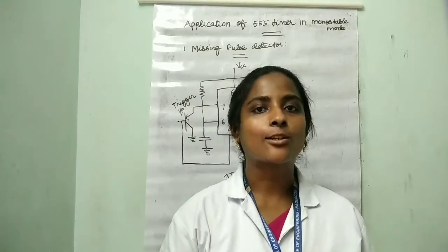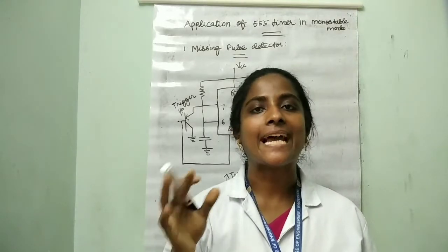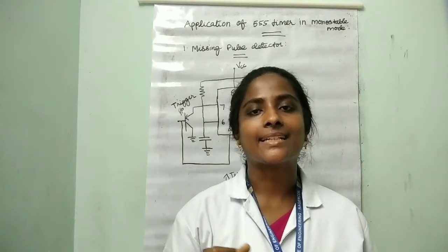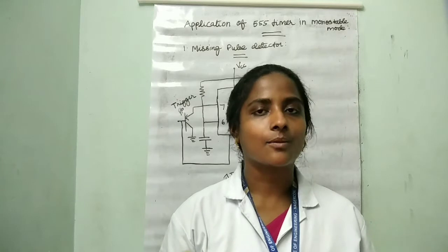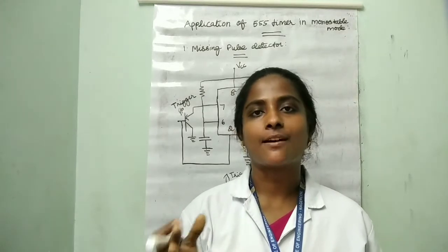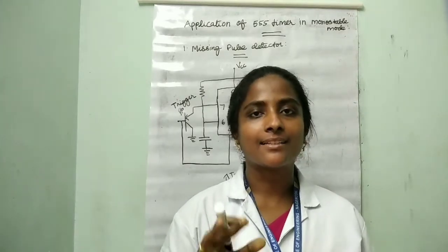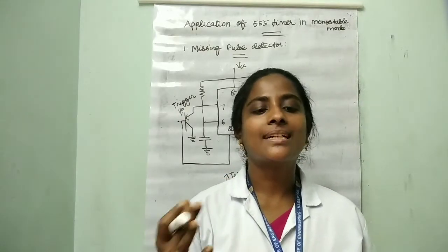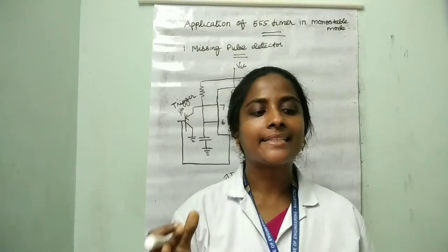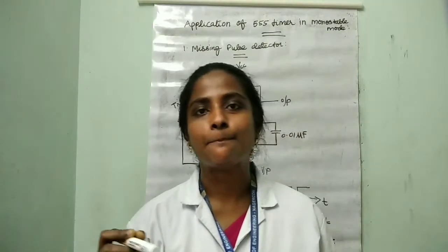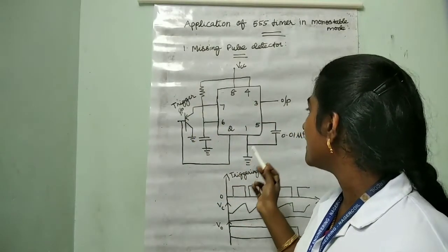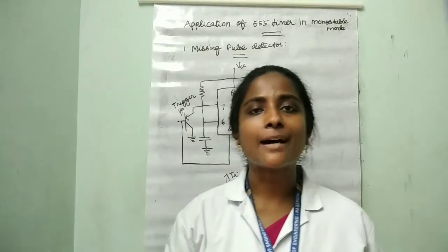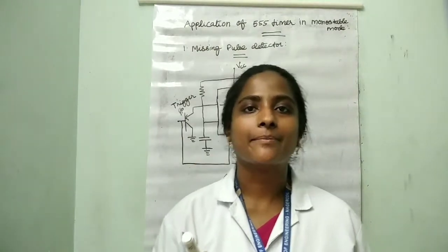The circuit is designed so that the time period of the monostable circuit is slightly greater, about 1/3 longer, than that of the triggering pulse. So the triggering pulse train keeps coming at pin 2, only the triggering pulse comes at this pin, and the output always remains high.